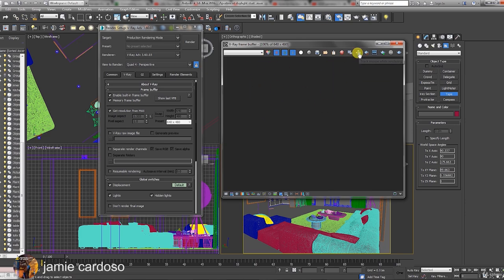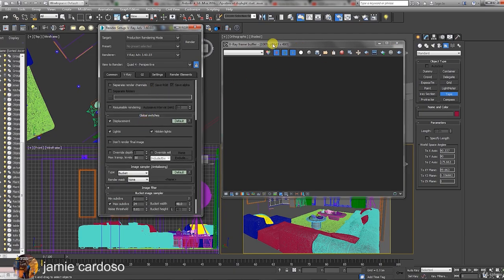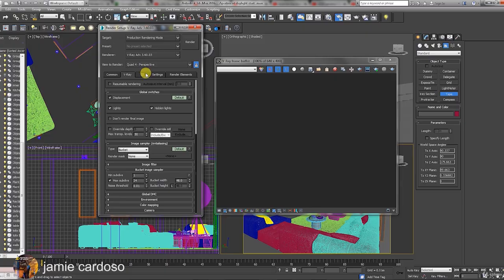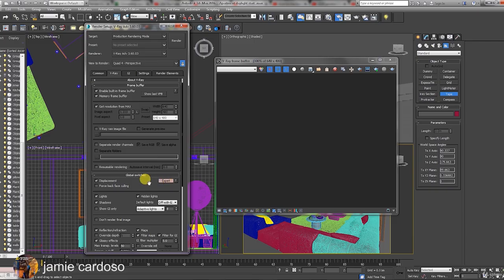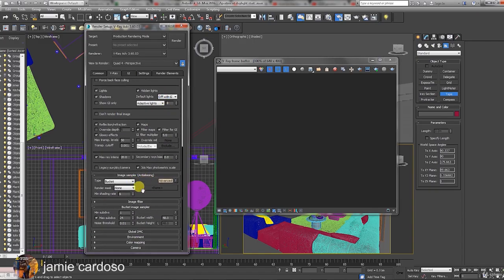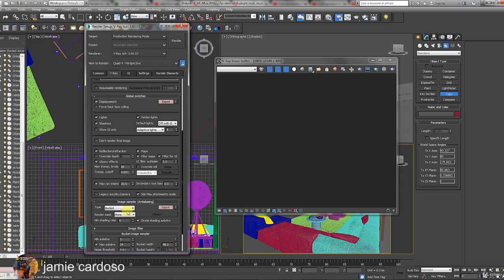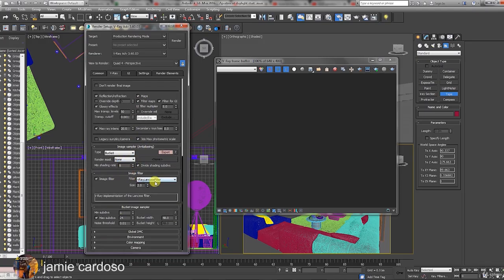Some of the key V-Ray settings are actually hidden under the default button. To make them visible, simply double click on each of the default buttons to expand the parameters. As you can see, after double clicking on a default button, it will turn into an expert type with all the hidden parameters on display. Under the image filter, choose the area type. However, feel free to use any of the other filters listed.